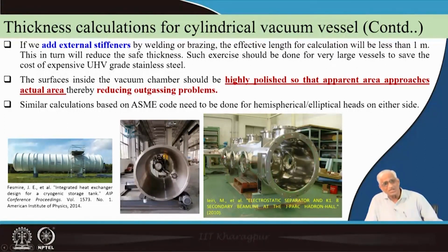Well, the story gets complicated as the pressure differences are increasing. And if the same chamber on earth has got a pressure difference, but if it goes to the space, outside also vacuum, inside also vacuum, then thickness can be very thin. But we cannot afford to do that, because to start with, the space shuttle has to go at atmospheric pressure. So, the design things come into picture. Once it is designed for a ground station, it is anyway safe, it goes into the space, because outer is also vacuum.